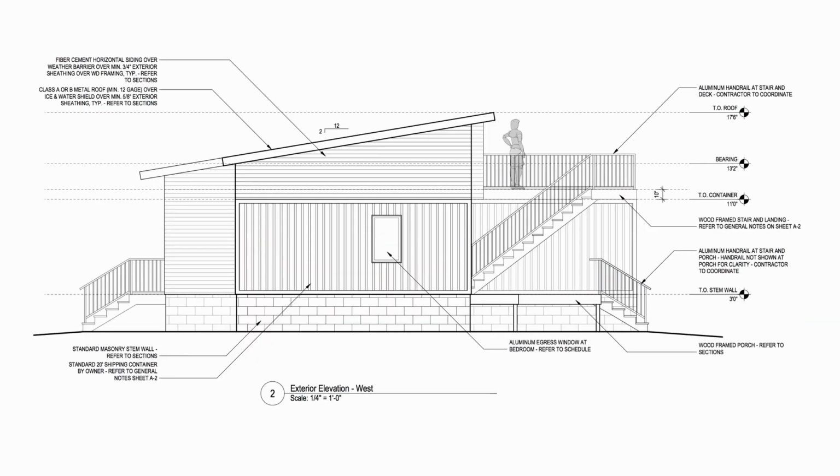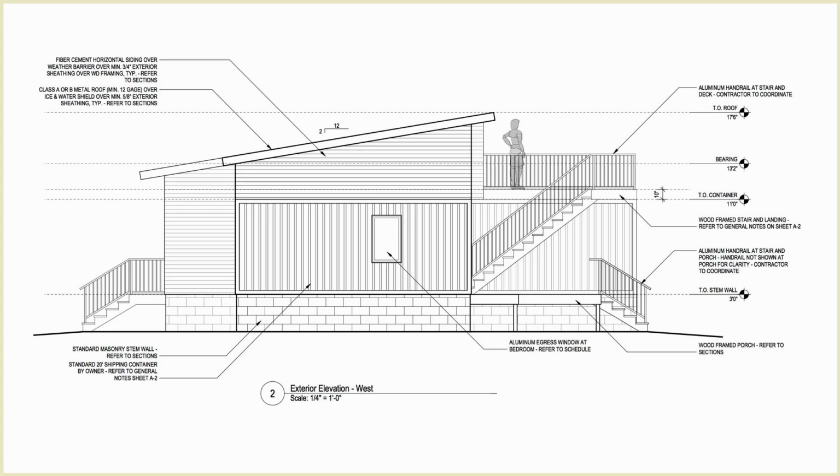Another example here, I think this one's pretty clean, and it's pretty easy to see the difference in the line weights. One of the things that I want to point out about this particular drawing is the way that they've changed the texture. So in this piece of the building right here that's coming toward us, all the lines and the textures are black. And when we step back to this section of the building, the textures have turned to a dark gray versus being a true black anymore. So they haven't gotten any thinner, they've just gotten lighter in their color. So that's another trick that you can use.